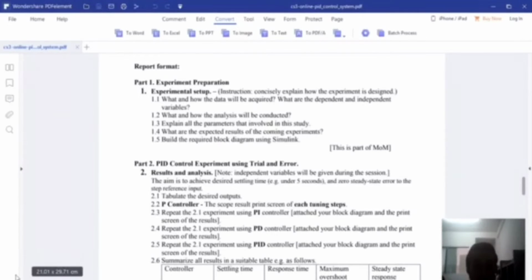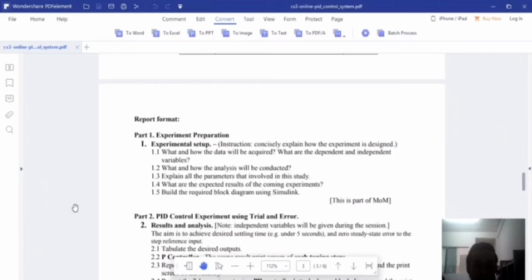Assalamualaikum warahmatullahi wabarakatuh. My name is Makmal and I'm from group 4. Okay, for this lab, in the experimental setup, to begin with the classical method, we use Simulink embedded software to get the transient response for open and closed loop. We use the Ziegler-Nichols closed-loop tuning, the second method, where we use the gain instead of the PID controller. So we begin with a low value of gain and increase it until a steady state oscillation occurs, where we note this gain as K-Ziegler.